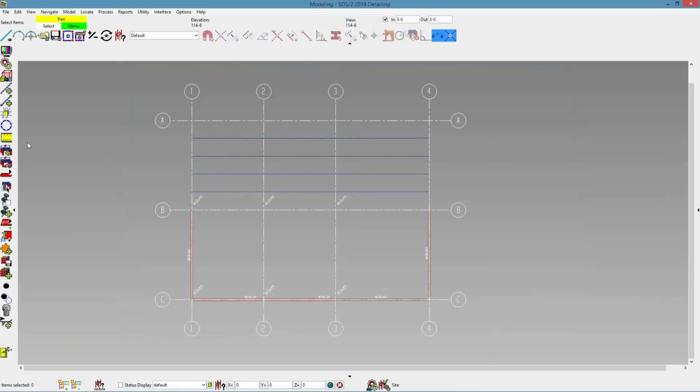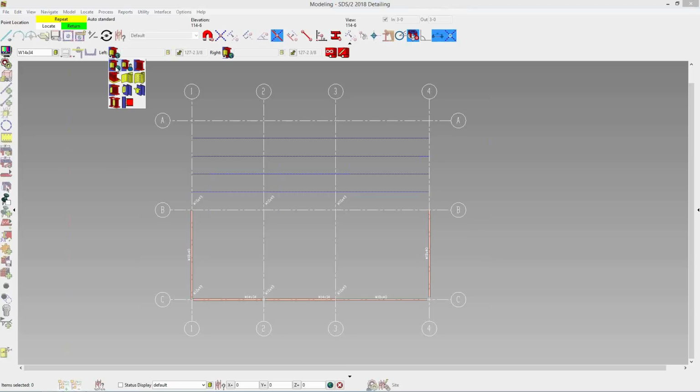So we'll start here with the beam add. When the member add options bar is enabled, when adding a beam, the common attributes can be found here. These are the section size, the toe direction, long leg 2, double material, left end connection. So if I pull this down, I can set it to auto standard, user defined, plain end, bent plate, clip angle, bearing, end plate, shear, seated, fully welded moment, or splice.